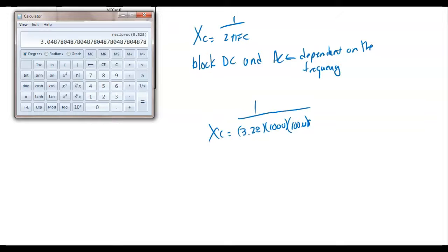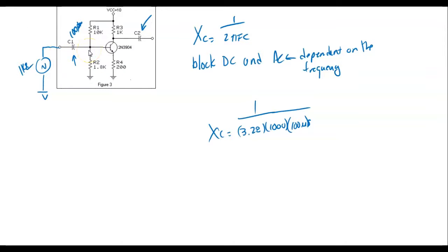So technically, if we choose the right size capacitor, we just ignore it. It lets the AC pass through it just like it's not there. 3 ohms relative to the 1.7K on the right hand side is nothing, especially when we start dealing with all the resistance. If I'd used a picofarad capacitor, it would be different, but on all your amplifiers you're going to see these capacitors in the microfarad range, giving 3 ohms worth of opposition.